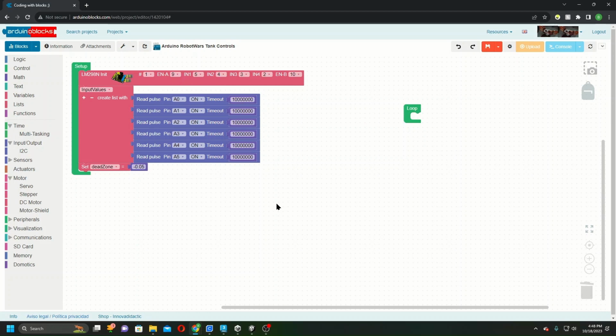what you'll notice is if you were to just read the raw values, especially with these Flysky controllers, or just about every controller, very rarely does it stay static on a number. It'll jitter back and forth, higher, lower values. Our dead zone allows us to set a range where we ignore the minuscule change that's happening so that we don't get that jitter within our program.